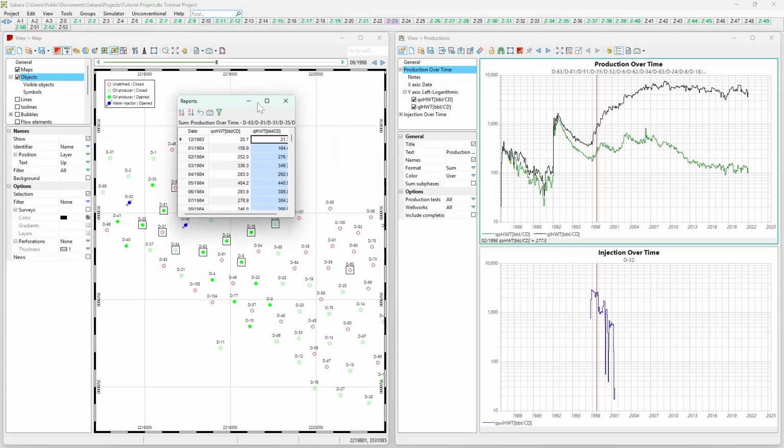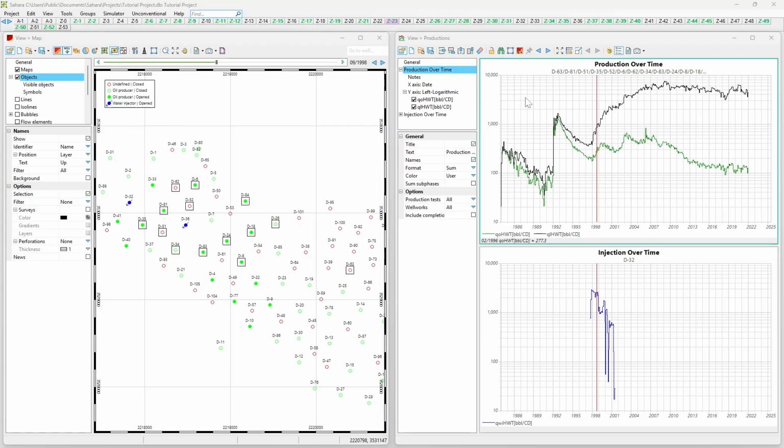So this is going to be in the report that we can copy here with this option of copy to clipboard, and we can, for example, export it to an Excel file using this button, or it's also going to be available if we use the mouse here and we want to see a specific value. See that on the lower side of the graph over here, we are going to see the date of the value that we are checking and the same initials, which means again oil rate of the history scenario at the well level, total subphase, and the units barrels per calendar day, and the total value that is 581 barrels per calendar day.